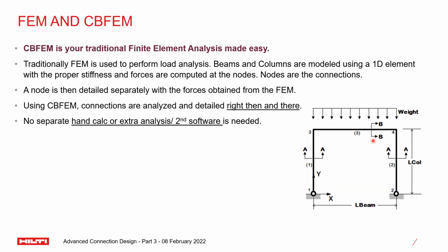And what do we do here? Well, we look at how the load is transferred from where it's applied all the way to the foundation using these beams and columns, where the load is transferred using the stiffness of the member, right? That's where finite element comes into play. And that's where the stiffness matrix comes into play. First, what happens? Load is transferred from the member to the node number 4, let's say, to this side.